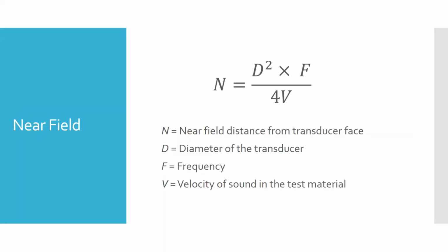So we got these big transducers like this. They're much better for composites, but they're not going to find surface flaws. They're more looking for things like delamination deeper in the material. Versus with metals, something like this smaller one's going to be better for finding cracks that maybe are a little bit closer to the surface.